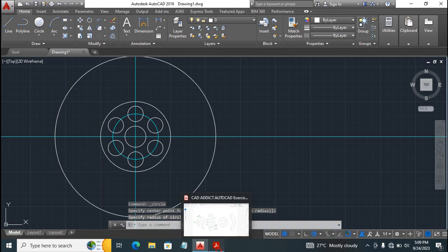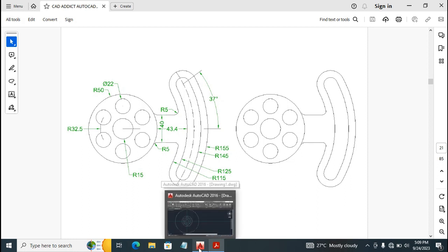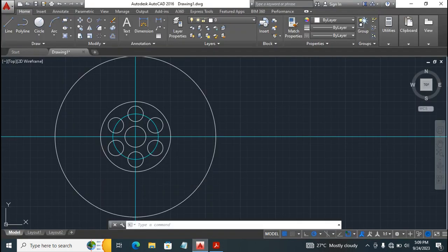So next up, go to CAD. We've got another arc here, and the distance between this first arc and this other arc is 10 millimeters. So we'll simply use the offset tool. Go back to CAD, go to the modify ribbon, then click on offset.